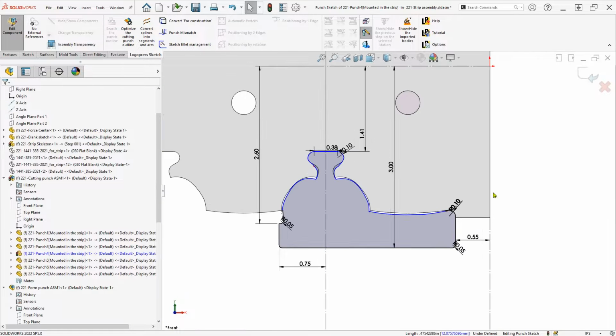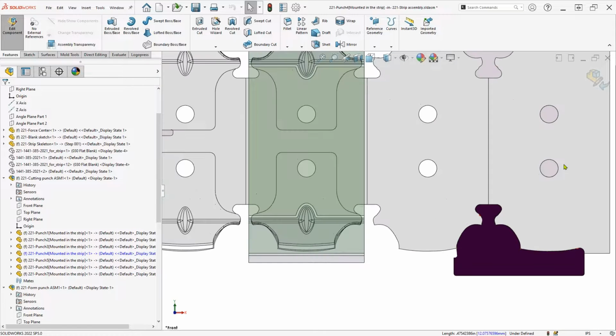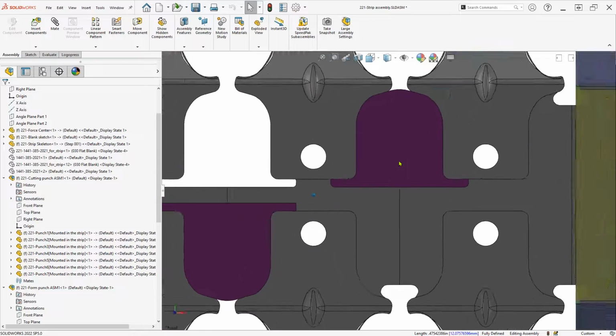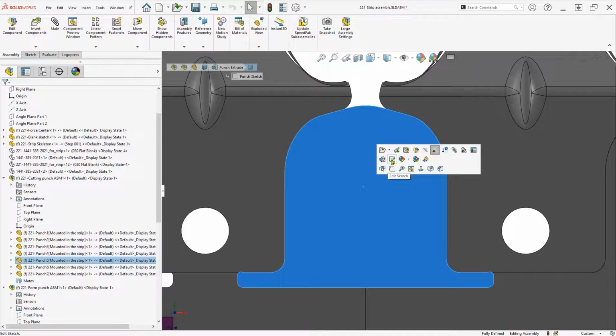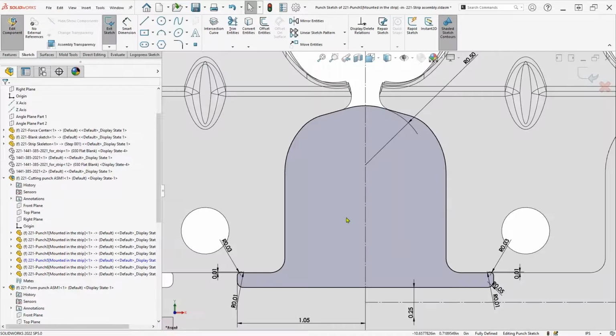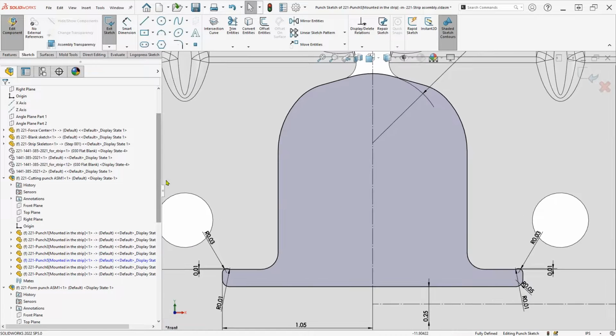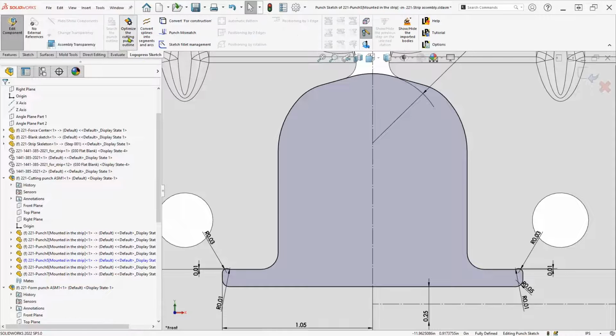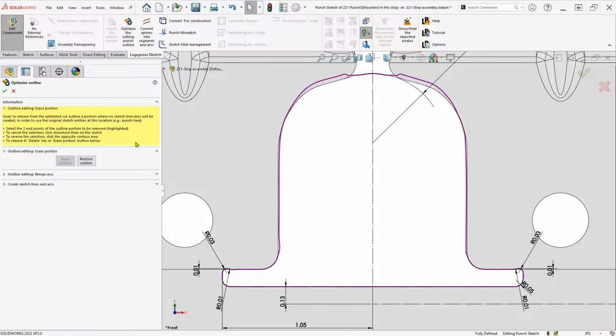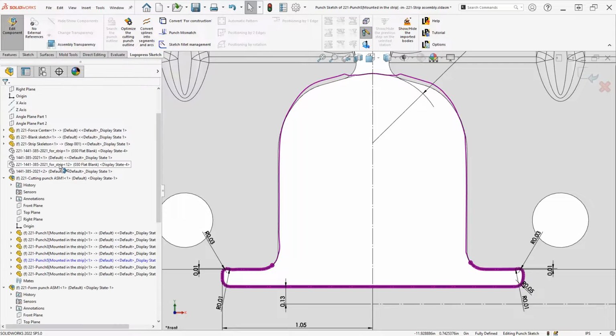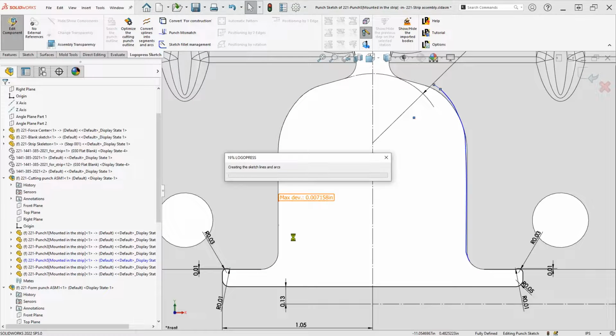So just note the first part of this presentation, we were really looking at formability of the part. Is this part going to pass or fail, or are there going to be issues? And now the last part here is where we're doing the developing of the blank. So again, picture how much shop time is spent in and out of the press. And this is a very tiny, very simple part, but when you get into bigger parts, it's well worth doing on a small, tiny part as well. But when you get to bigger parts, it's just so much more valuable. It's incredible.